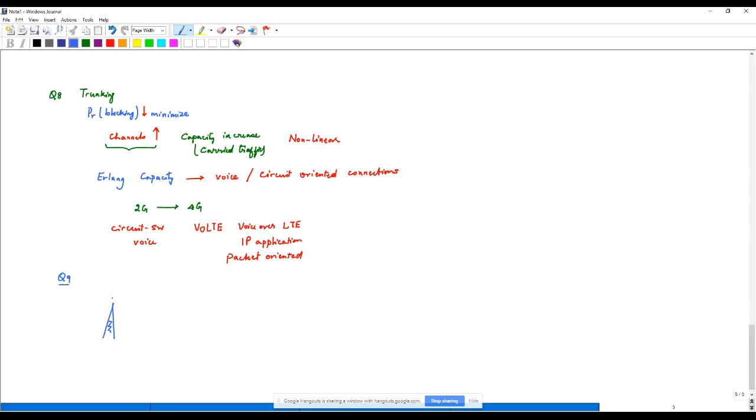The base station, as we discussed in the lectures, has a triangular grid on the top, basically for the 3 sectors, and has antennas. If I look at the antennas on the base station at the top, the antennas are actually down tilted. Why is that? Because the base station is at a height of 25 to 40 meters, and most of the users are on the ground. So therefore, my radiation pattern must be focused more downward. So there is a down tilting of the antenna.